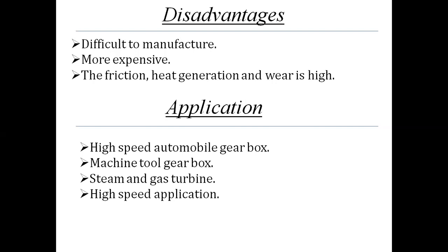The friction, heat generation and wear is high. So generally these helical gears are continuously used with cutting oil, and in some applications these helical gears are continuously dipped in the cutting oil to carry away the heat which is generated during the operation, to reduce the friction and wear, and to increase the life of helical teeth.